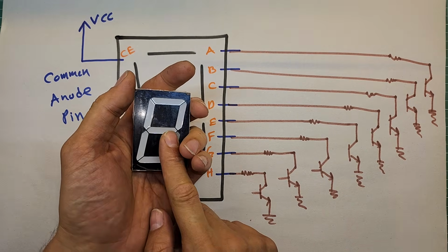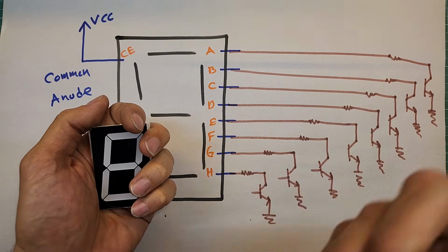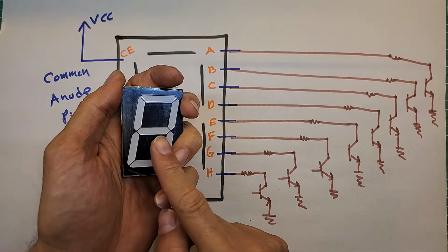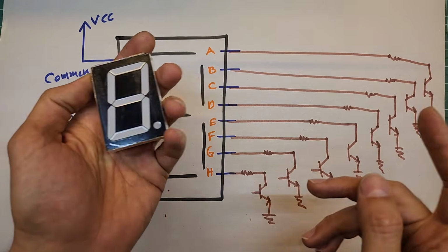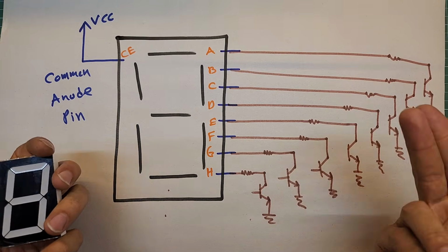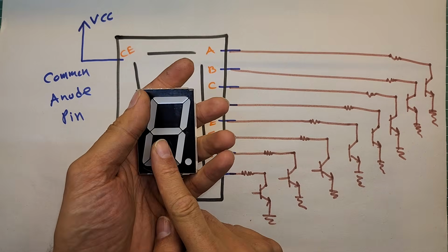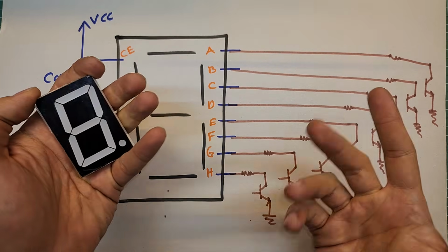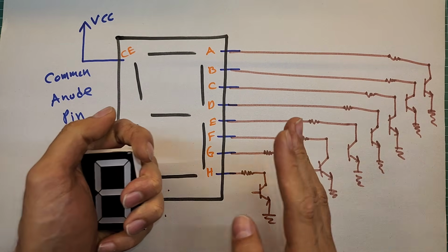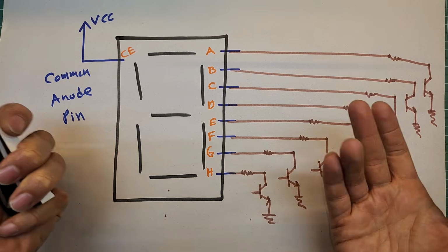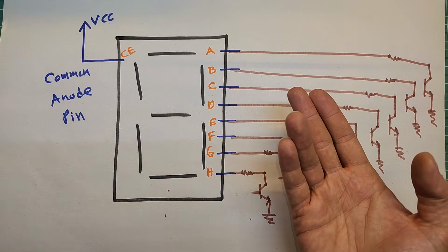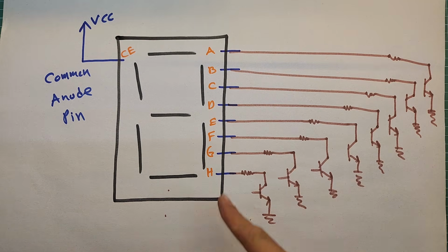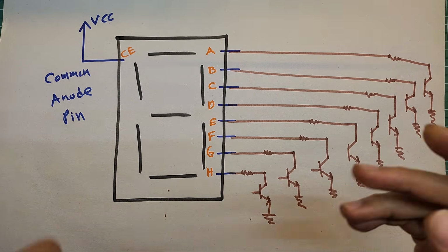Sometimes the 7-segment display we are using might operate at a different voltage compared to the IC's operating voltage. For example, the 74HC595 IC works with voltages between 2 and 6 volts, but our 7-segment display might work with 12 volts, for example, or the LEDs on the display might have higher power and require a lot of current to light up, which the IC's pins might not be able to supply. In this case, we need to use a transistor circuit to switch the voltages to the 7-segment pins on and off.